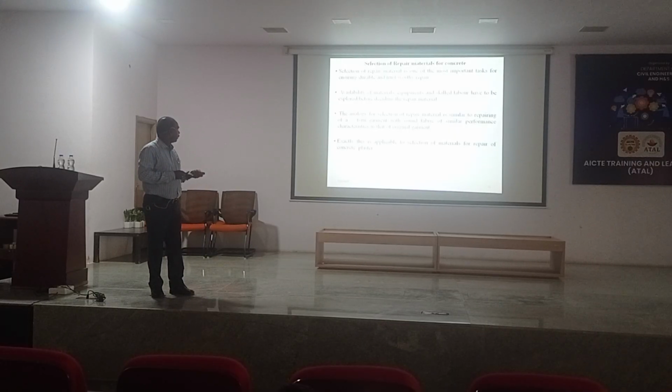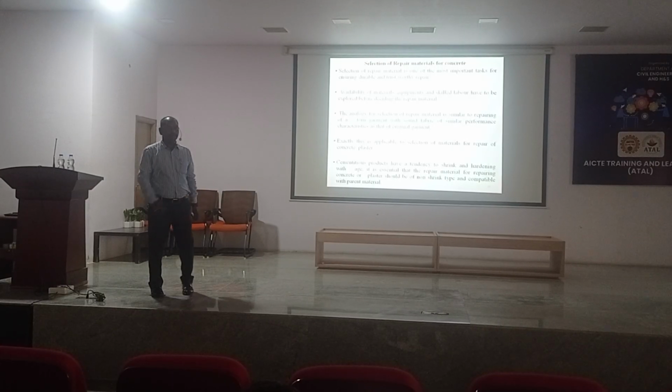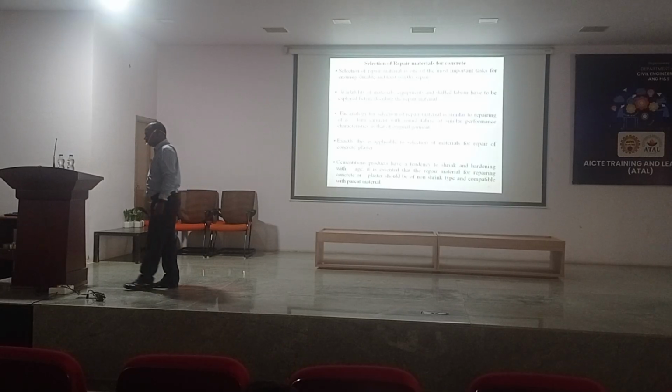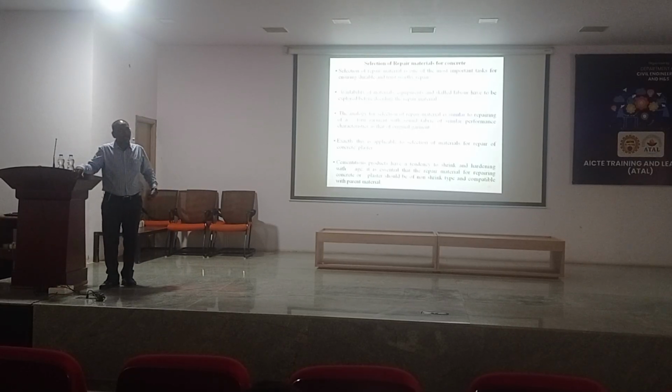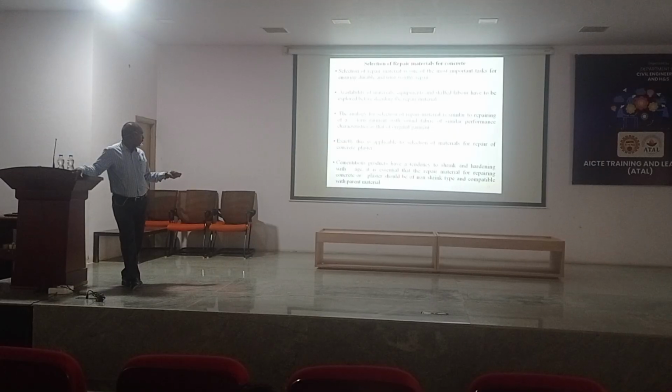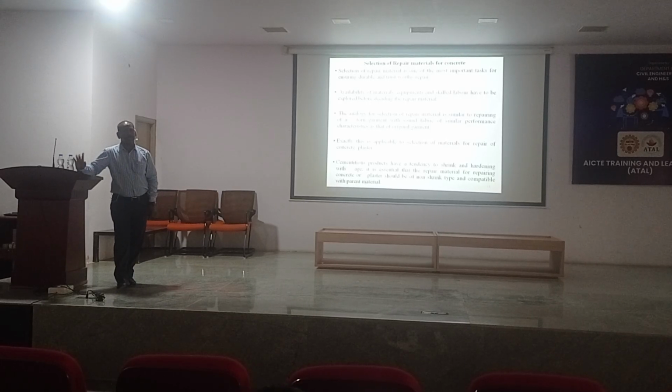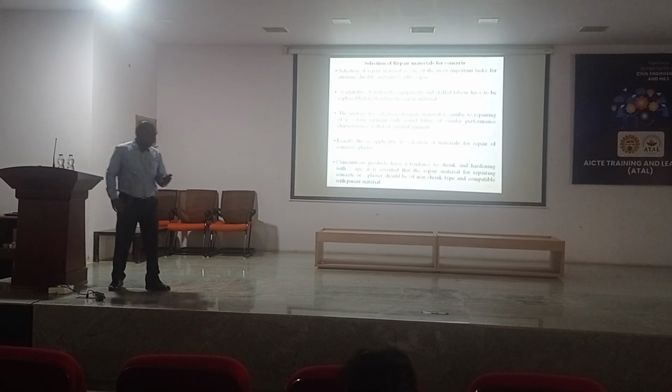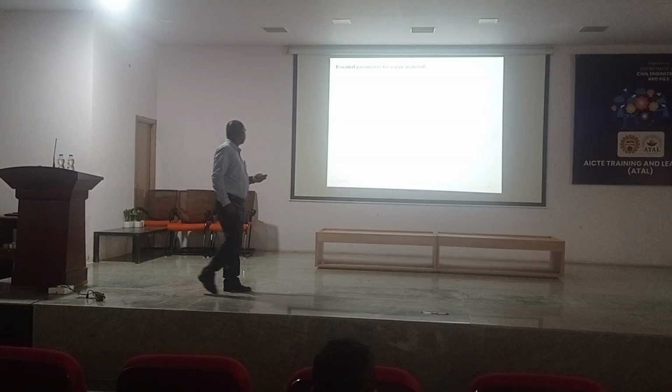Okay, this is applicable to the selection of repair materials. Yeah, this is the main problem. Shrinkage is the main problem. Therefore, you cannot go for a higher amount of cement. Cementitious products have a tendency to shrink and harden with age. Therefore, you should select a repair material that is non-shrinkable. Okay? Non-shrink type. Then one by one, we will discuss those properties here.